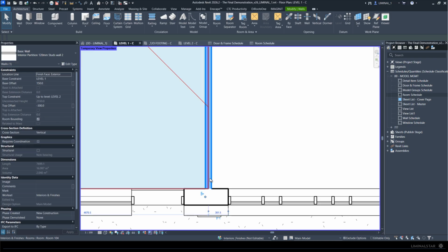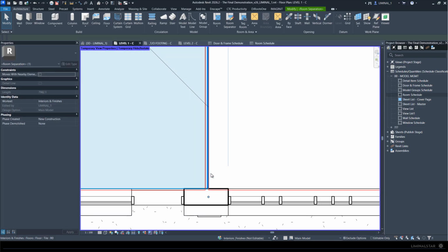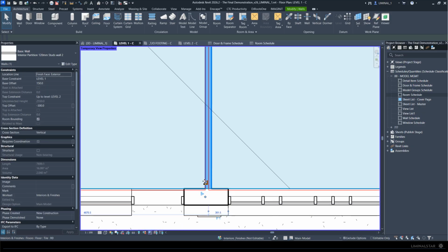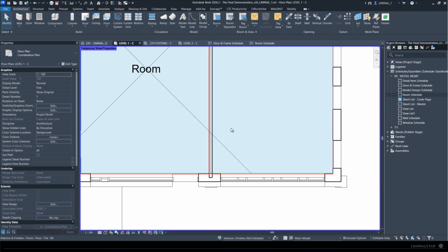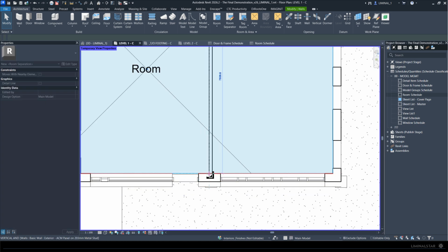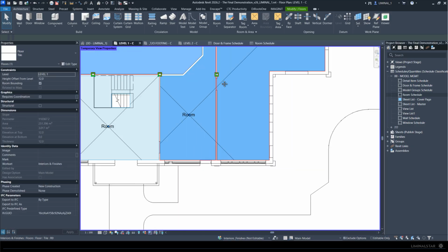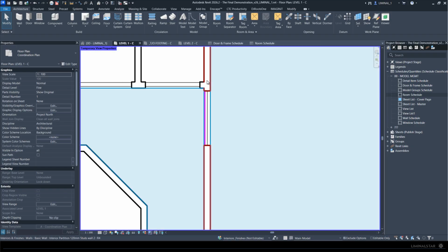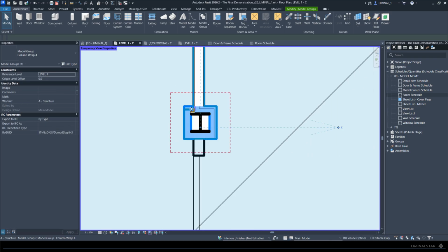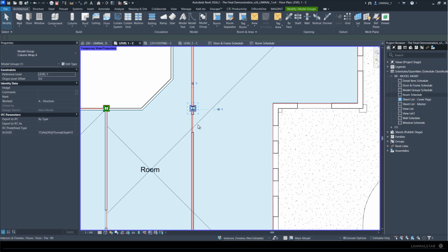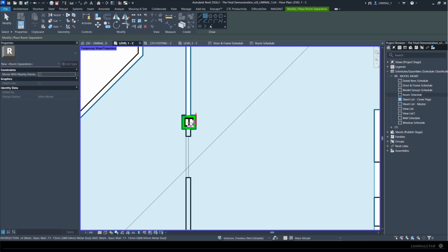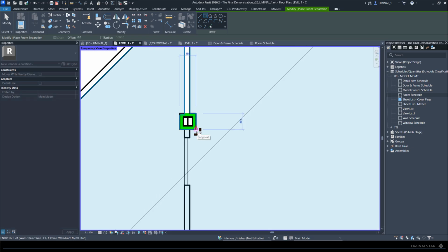Right. If I hide the wall, we can see our line, then we can bring that back. That's still not fixing that issue. Right, so what's probably happening is right in here, because I believe we have this set up as a group. So maybe our room separator should just be a rectangle.